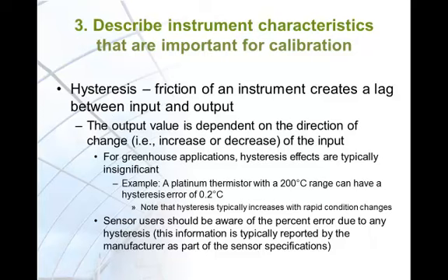For example, Licor and Apogee use silicon detectors rather than selenium detectors and claim that this eliminates hysteresis effects. A humistor from Vaisala claims a 3% hysteresis error over its 10 to 90% relative humidity range. This is an error of 2.4%. A type K thermocouple can display hysteresis errors if brought to extreme temperatures, such as 1000 degrees Celsius, that are never seen in the greenhouse.